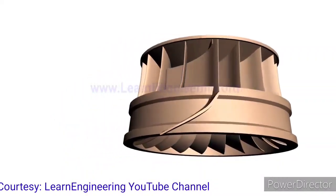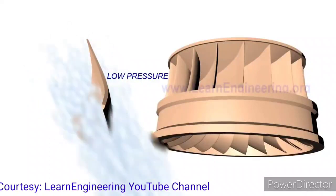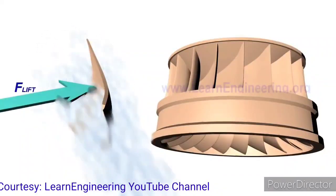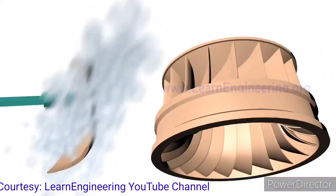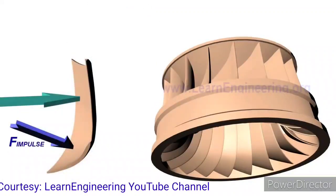Francis turbine blades are specially shaped. You can note that the blades have a thin airfoil cross-section. When water flows over it, a low pressure will be produced on one side and high pressure on the other side. This will result in a lift force. You can also note one more peculiar thing about the blade. It has a bucket kind of shape towards the outlet. So water will hit and produce an impulse force before leaving the runner. Both impulse force and lift force will make the runner rotate.